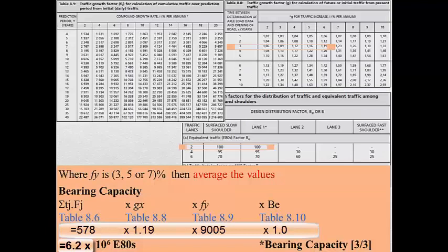And finally, by selecting a compound growth rate. In this example, our structural design period is 20 years. Our growth factor is 6%, therefore our number is 14,232. Where the growth rate is an uneven number such as 3, 5, or 7%, we would take the two even numbers and average them off to get our answer. Where growth rate is not given, students may use 6%.